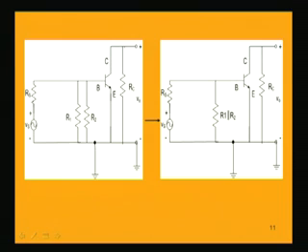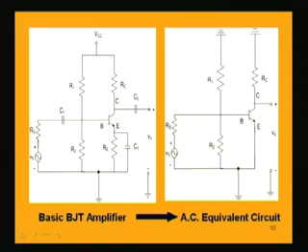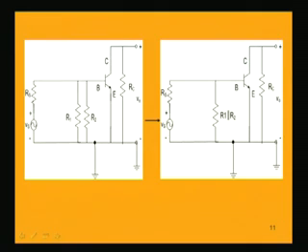Also, this RC, if we look back, is grounded from the collector, but most commonly it is not drawn upwards. Ground is always shown downwards, and that is why conventionally we draw it again by connecting the collector through resistance RC to ground. This point is ground. So, this is the conventional circuit which we have derived from the transistor amplifier, applicable under AC. The AC equivalent circuit is this one.